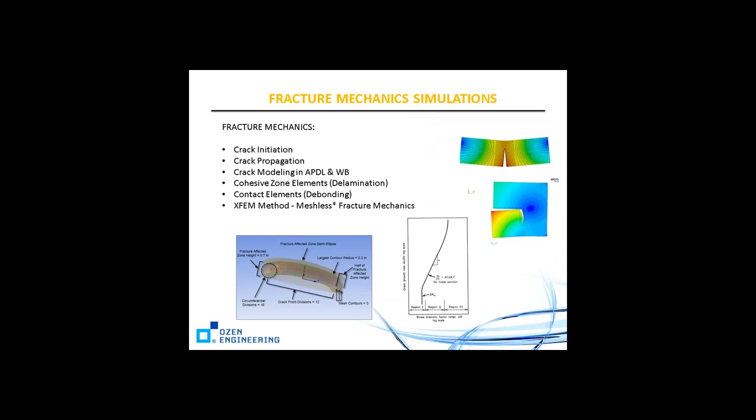In addition, we also have special expertise in fracture mechanics and CFD. Our next lunch and learn will be on fracture mechanics. So we are going to talk about crack initiation, crack propagation, crack modeling, cohesive zone elements, contact elements, and then we call this XFEM method, which is meshless fracture mechanics. There's actually a mesh, but you don't need a special crack tip element, just like you see here. So when it comes to meshing, this is a special topic.